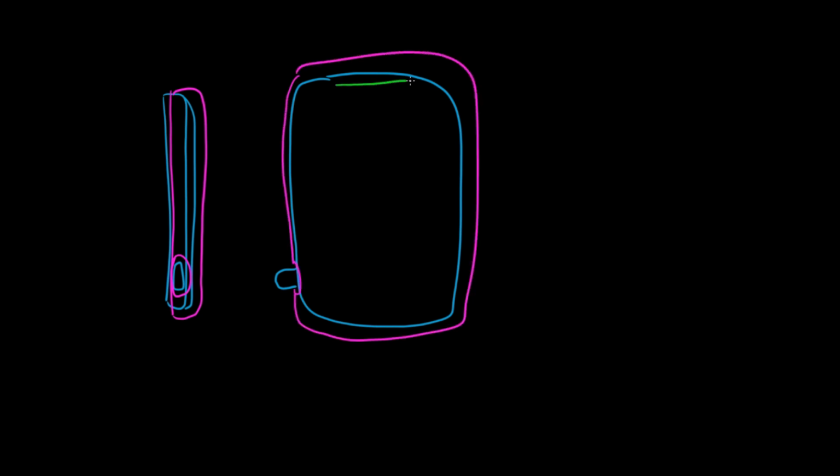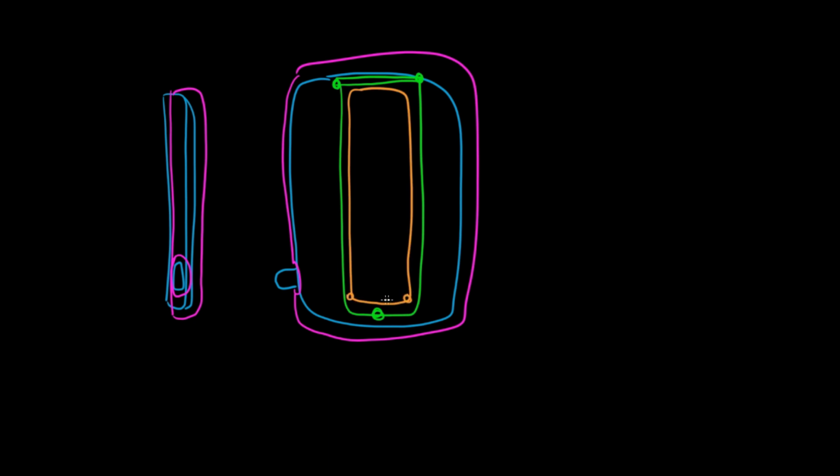So in essence, if we're looking at the back here, here's the antenna again. We have a casing that's form-fitting. Then we have a piece that comes out, and we can say that this is where it can pivot from. So you would pull from here and it would swing open, and underneath that we would have another one with a pivot on the opposing side. So then you can get it from here and open it out. And so what that would do is give you the ability to open the top flap while having the bottom flap be a support. And likewise, if you were to need to flip the screen so that the antenna portion's on the top, you can likewise flip the opposing end and use the smaller end to hold it up.